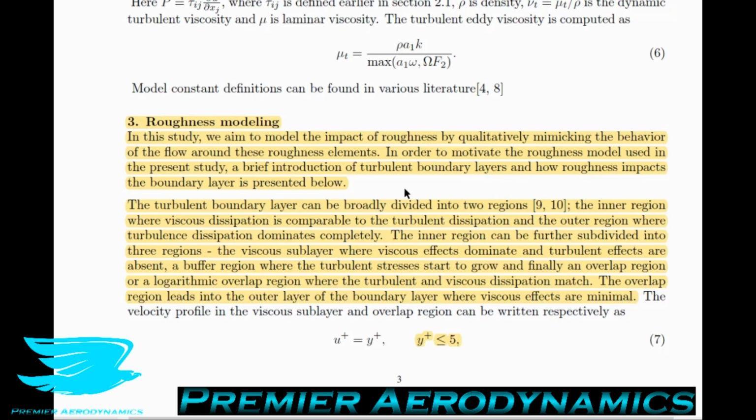I just mentioned a few different points in the boundary layer. So we have this viscous sublayer. And in other podcasts, when I've talked about CFD, I've talked about the Y plus value. And this is effectively how well resolved the flow near the wall is. And the Y plus value you typically want to have below 1.